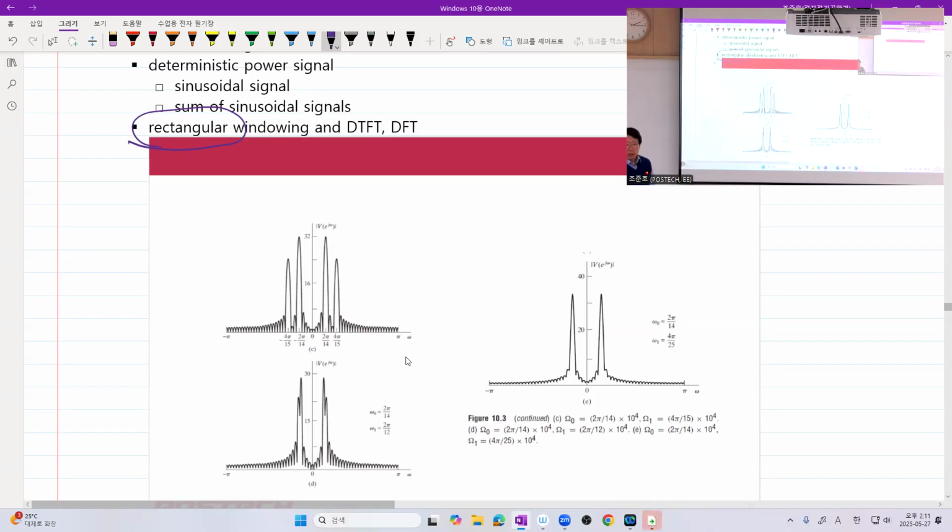That can be done by a clever design of a filter, or sometimes in a uniform linear array, you modify the weights, the complex gains multiplied to each output of the antenna element. You can shape the radiation beams anyway.